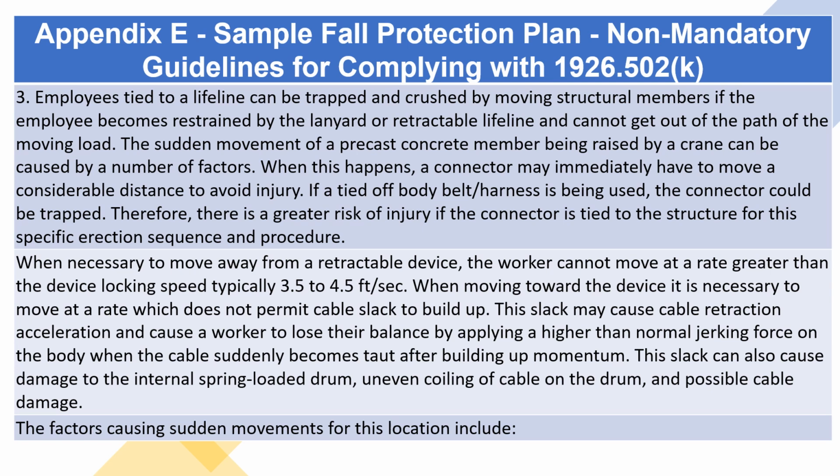Therefore, there is a greater risk of injury if the connector is tied to the structure for this specific erection sequence and procedure. When necessary to move away from a retractable device, the worker cannot move at a rate greater than the device locking speed, typically 3.5 to 4.5 feet per second.